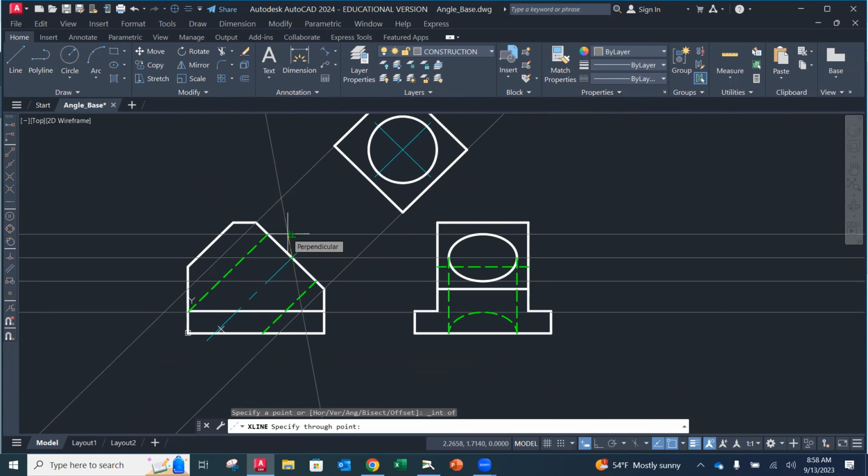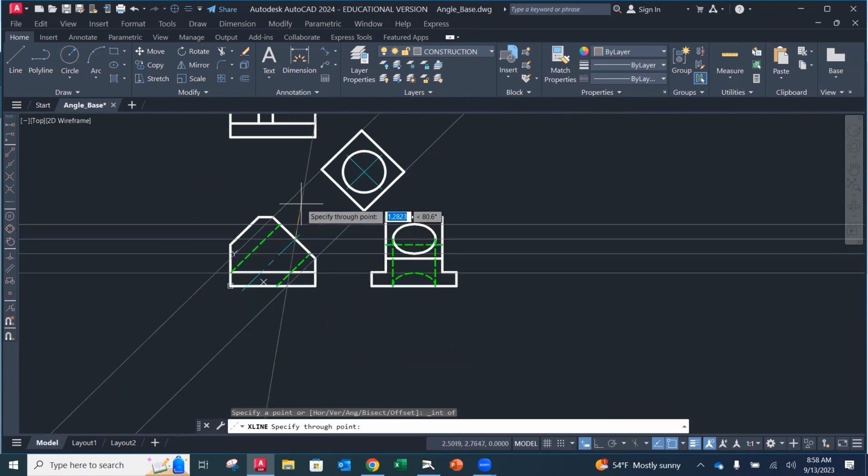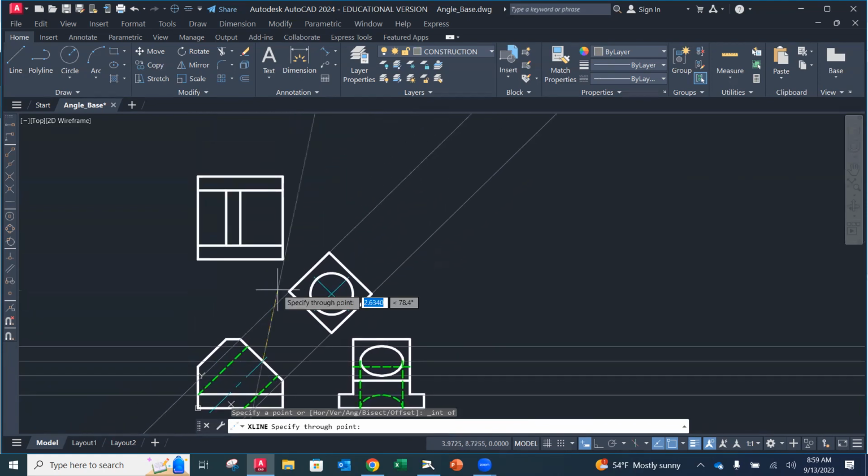Be careful with those, especially when you have multiple things. I added midpoint, and now they start grabbing midpoints, and the midpoint might not always be exactly right. It might be close, and then that's when you start getting things off. I've had some students say, well, I'm off by little bits. It might be that you're using object snaps, but the wrong ones might be grabbing, unfortunately. So make sure that you're very intentional about which ones you're using.